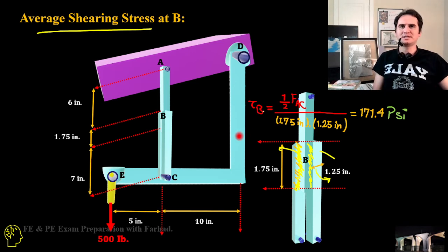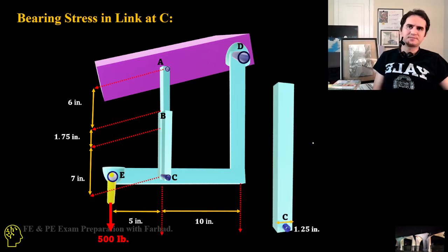It gives us a bonding stress, tau b, equal to 171.4 psi. You can easily compare that with the shearing strength of something like 2200 psi, higher than that, and this is less than 200. So the epoxy resin can handle a far smaller amount of shear in comparison to other parts.